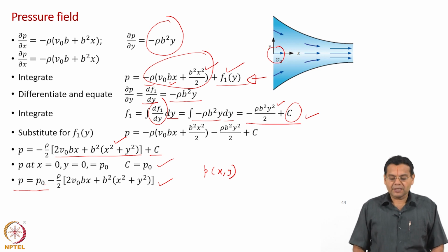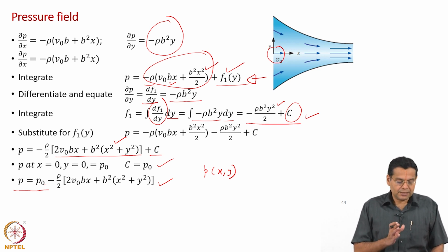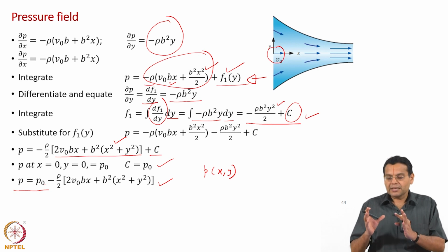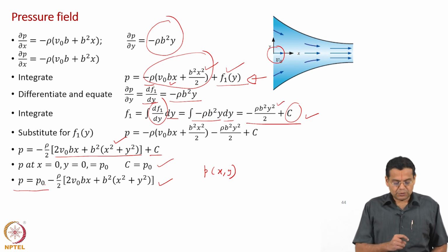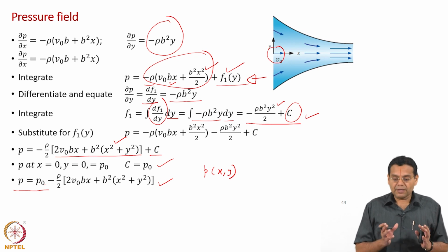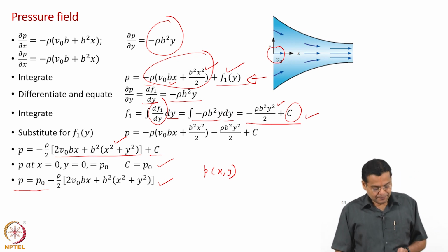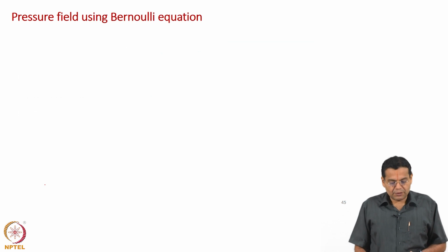In the case of incompressible flow, if you want to say it more formally, we always find pressure up to an arbitrary constant or arbitrary given value of pressure, and that is what is clear from here also. Even in the earlier example, we found pressure gradient, we never found pressure. So, pressure is always given, or we always find it in terms of pressure difference. Okay. Now, what we will do is